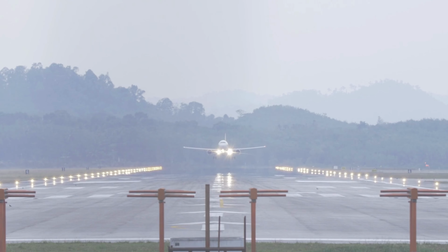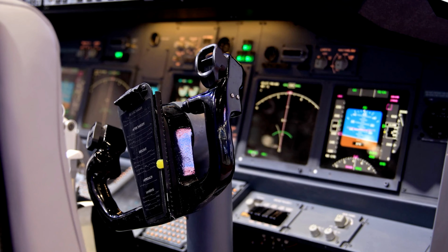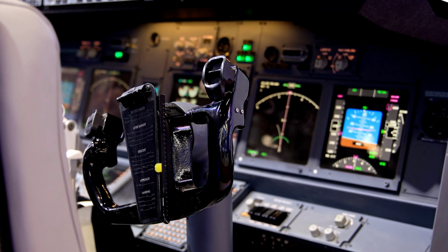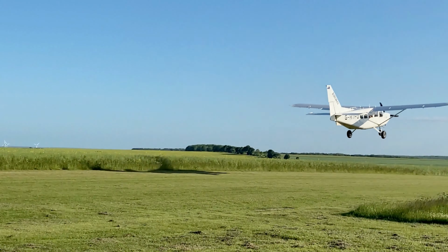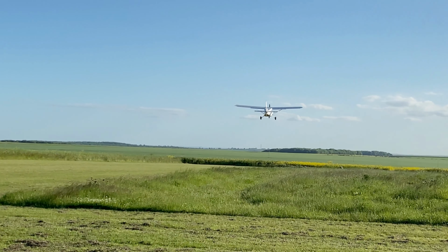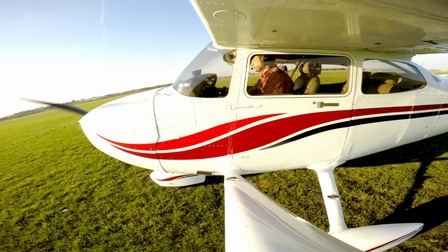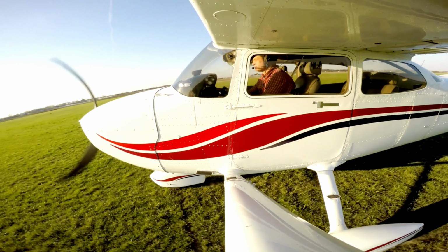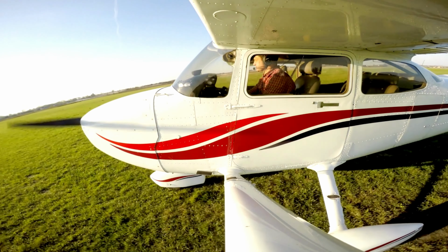Air traffic control doesn't just make sure aircraft don't collide with each other, they also direct aircraft to avoid each other's wake turbulence. Generally, they'll be using procedures for separating IFR traffic, but they may also issue guidance for VFR traffic. VFR traffic flies under the see and avoid approach. It's the pilot's responsibility not just to avoid collisions with other aircraft, but also to anticipate their wake turbulence and